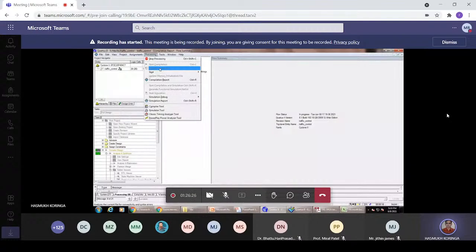Once we get the correct functionality, then do the full compilation, because a full compilation takes time. It does all the tasks like analysis and synthesis, then the fitter, then the assembler, and lastly timing analysis. So for that it takes the time.